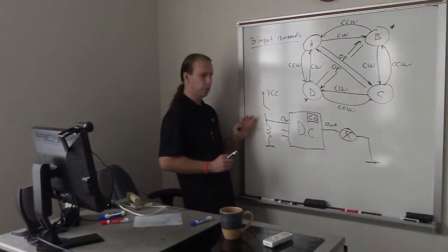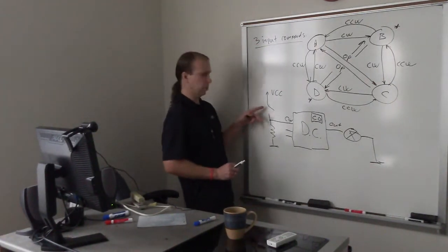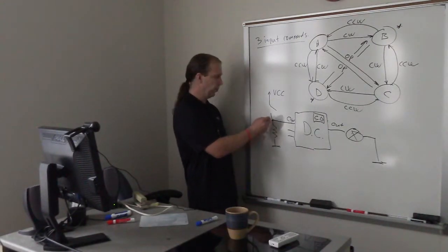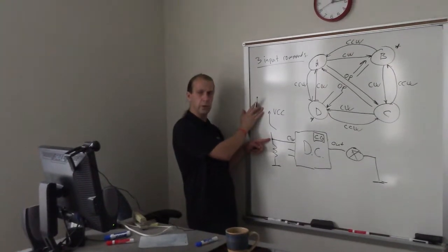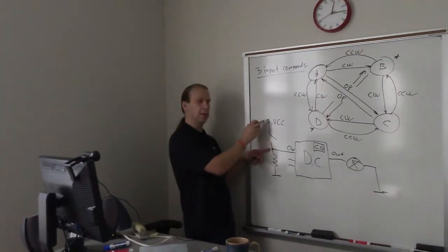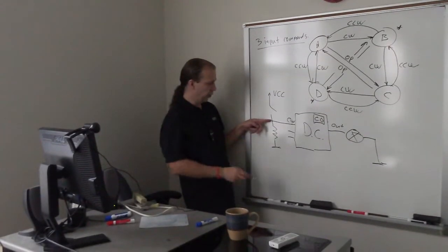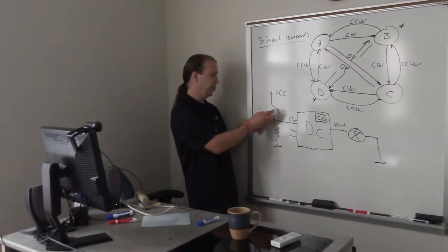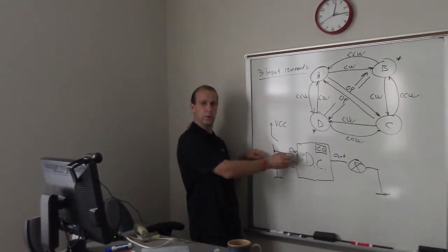How does this switch work? If the switch is open, open means not closed, what will be the voltage here? The voltage here will not be sourced by the voltage source, because the voltage source is disconnected from this point. And at this point, the only voltage we have is zero level. So in other words, when the switch is open, our signal will be 0.